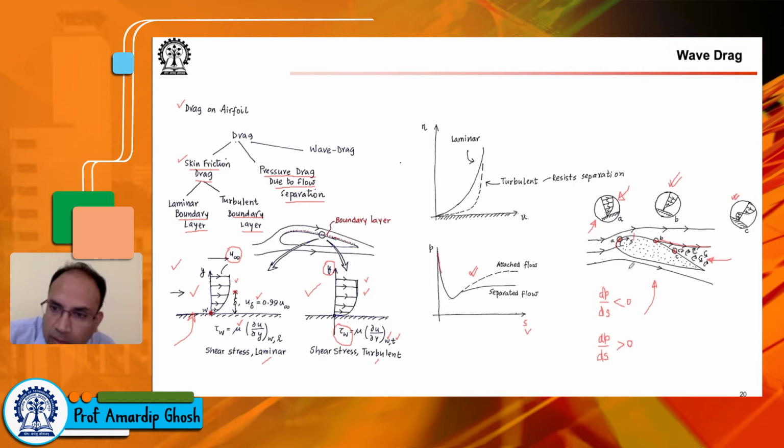In the case where the flow did not separate, it is not necessary that if you had an adverse pressure gradient, the flow has to separate. It depends on the magnitude of this adverse pressure gradient. And if you think of inviscid flow analysis without boundary layer, then the flow of course will not separate. In those kinds of analysis, if the flow is attached, the pressure in the rear side, in this region, recovers to a certain level.